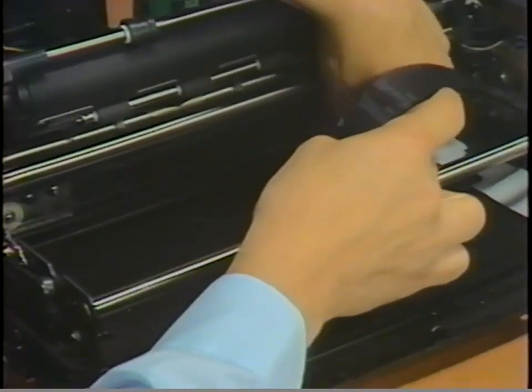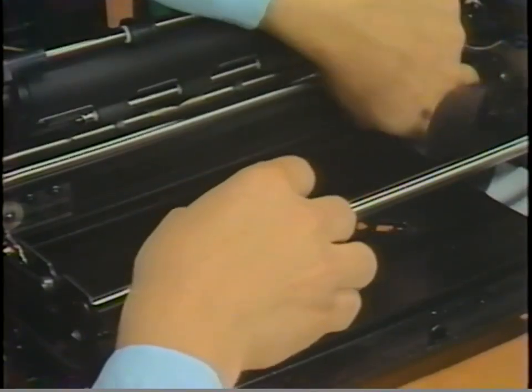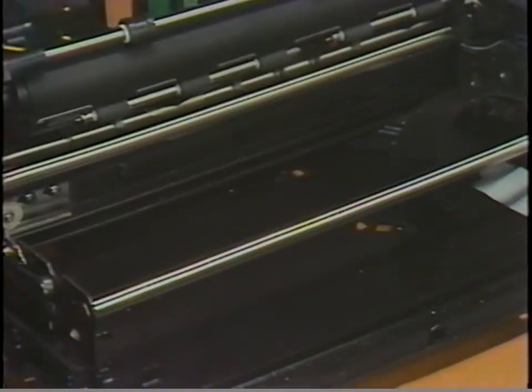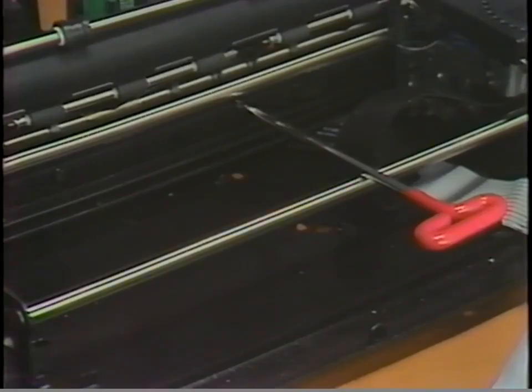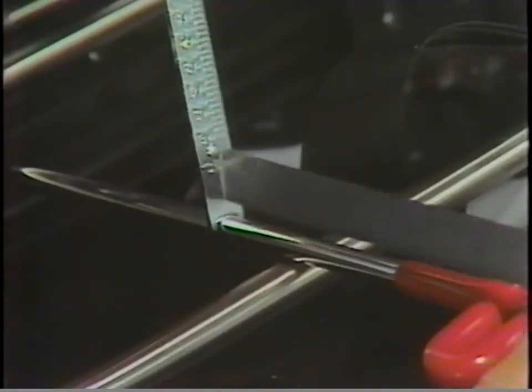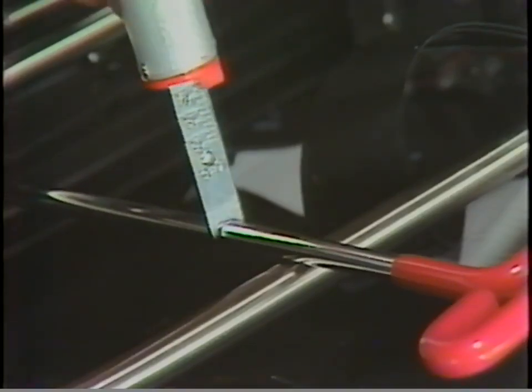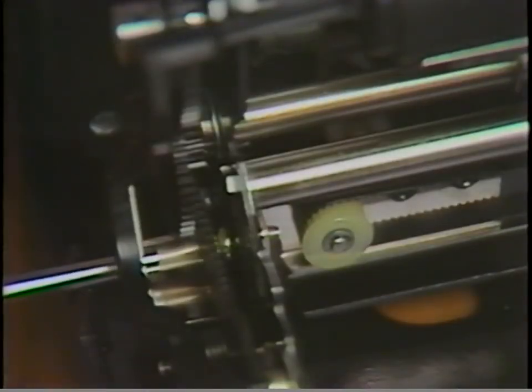Then slide the T-bender over the top of the transport belt at its center and rest the T-bender on the front shaft. Place the spring scale on the T-bender 30 millimeters from the center of the shaft, apply 6 pounds of pressure on the T-bender, and turn the adjusting screw in or out so that the bottom of the T-bender just touches the bottom transport belt.